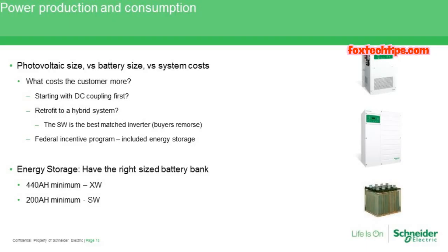And with AC coupling, this is assuming that we're using the efficiency of the grid tie inverter when the sun is shining. So as little as 4%, with a grid tie inverter and the wiring losses in there, that's where we get that 4%. For non-cycling applications with battery backup, it really comes down to when you're going to use that system and what the customer's looking for. So if they are looking for just offsetting a power bill with, let's say, net metering and that's it, well, great.